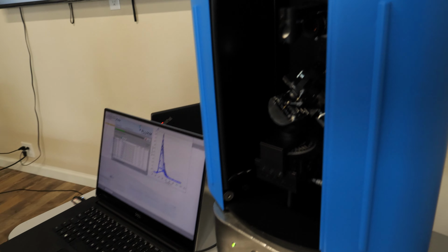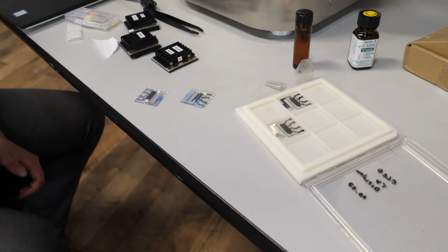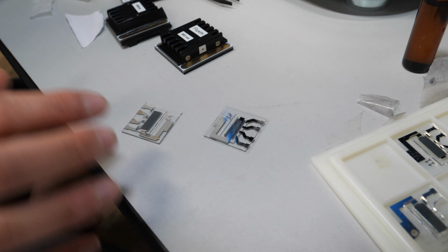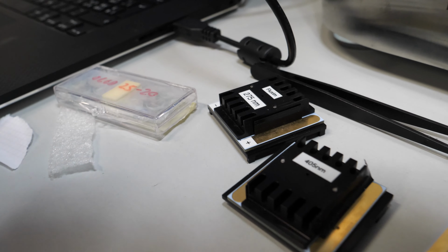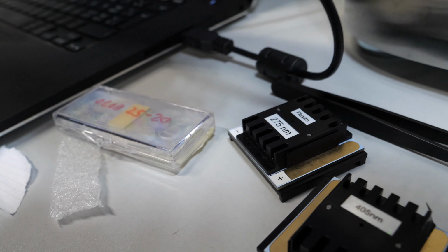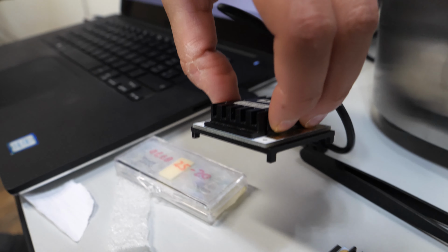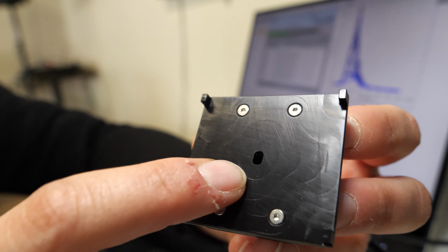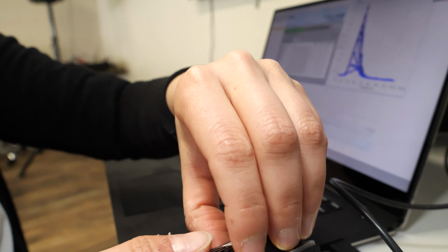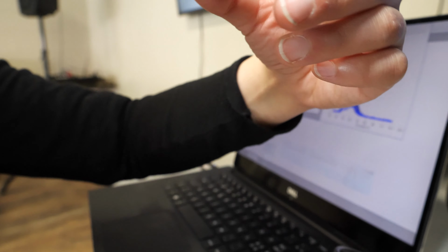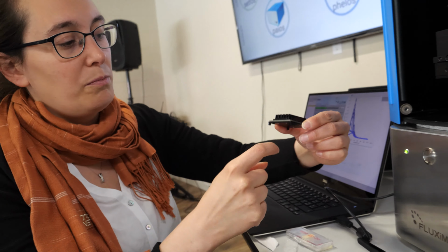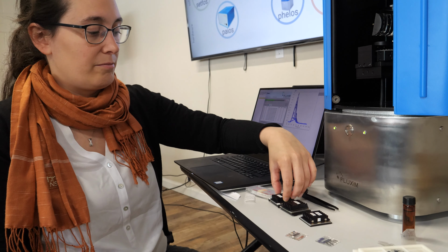Nice. So you have the whole system, so you can easily set up all these different samples. What are these different samples? So these are just different OLEDs with some different layer thicknesses, and these ones are PL samples. So instead of putting an OLED on top, we can also put a PL film, so a single emitter film, and then put this. Can we look around? What is going on here? So there's a hole, and inside there is a UV LED with 275 nanometer wavelength. And then you just excite your film from the top through this hole, and you also measure the angular dependence of the photoluminescence.